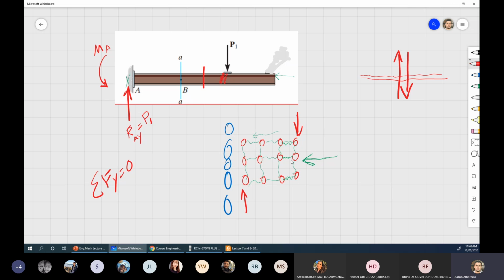Now, if the force wasn't axial, if it was in this direction, perpendicular to the member, it's the same thing. If we reach a point here that's too strong, these springs will stretch too much, and this may shift these particles. This will cut from here, and this particle here will find itself closer to that point rather than that point. So we'll shift a little bit. And that will cause a slight deformation as we go further until all the joints between the particles cut and are sheared, and that will be the ultimate failure point. So just to go back and answer your question simply, shear force is the force applied perpendicular to the beam. It's this type of force.